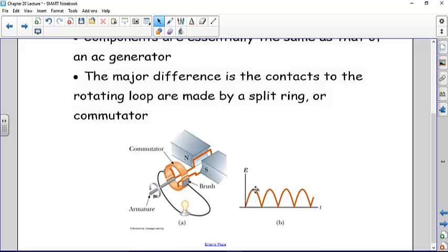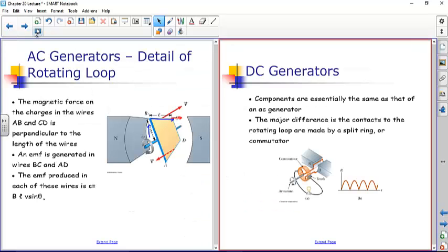Now this is not DC, so what you would ultimately have to do is put some kind of a capacitor in there, and a capacitor would even out this. It would flatten out the voltage. It's like you're pushing somebody on a swing and you're always pushing in the same direction, kind of thing. So you can kind of think of you pushing it as this, but the inertia of the person is going to keep them moving.